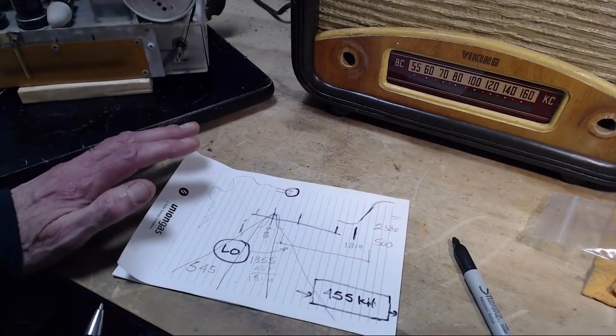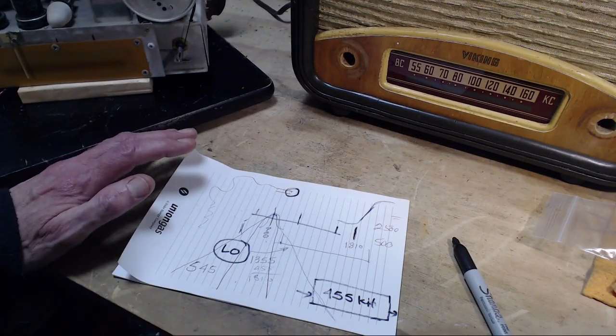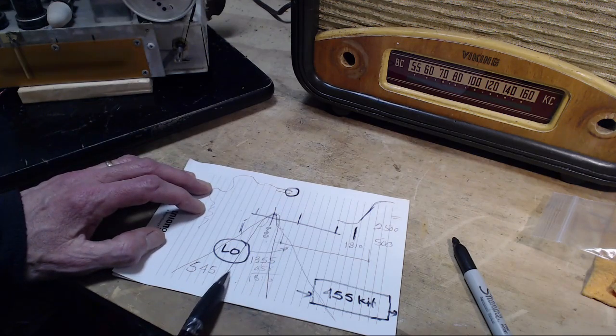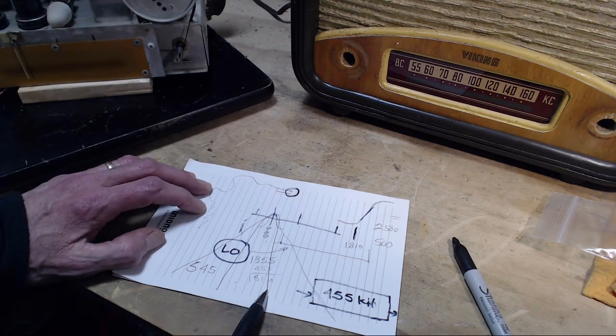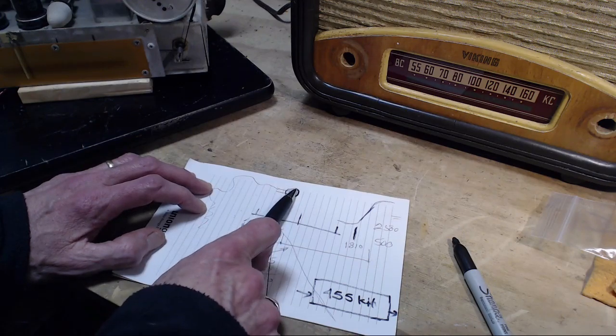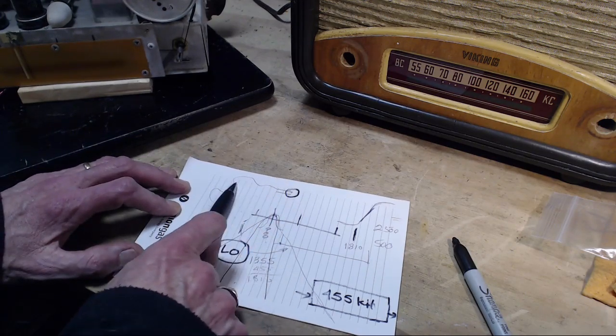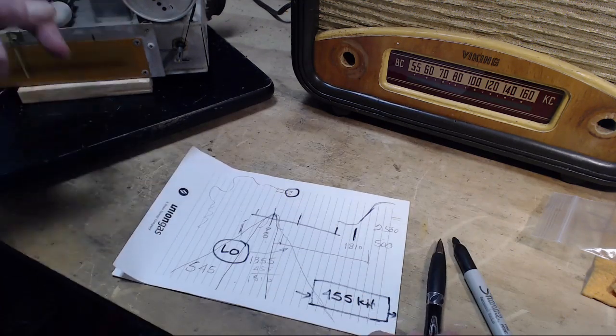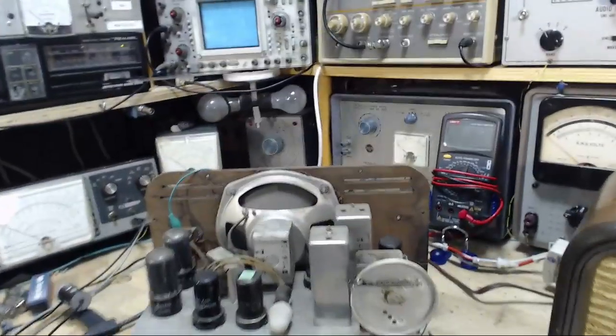So when judging the quality of the radio, one of the things you want to do is figure out how steep this front end curve is before you get to the mixer tube, or how many stages there are ahead of the mixer tube. So we look at this radio right here that I've just been working on.